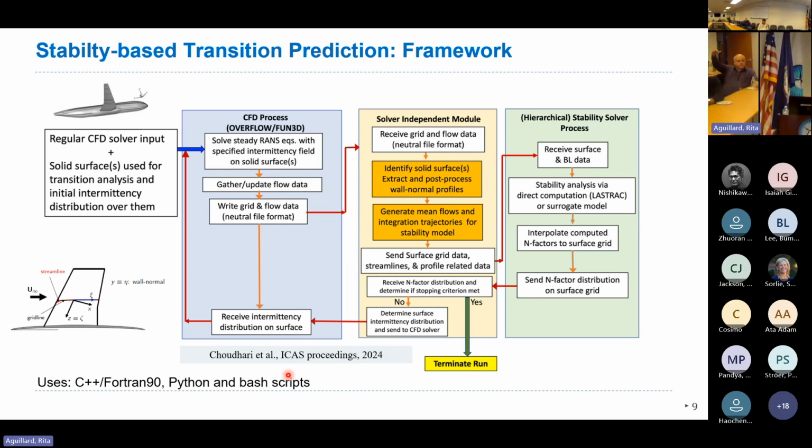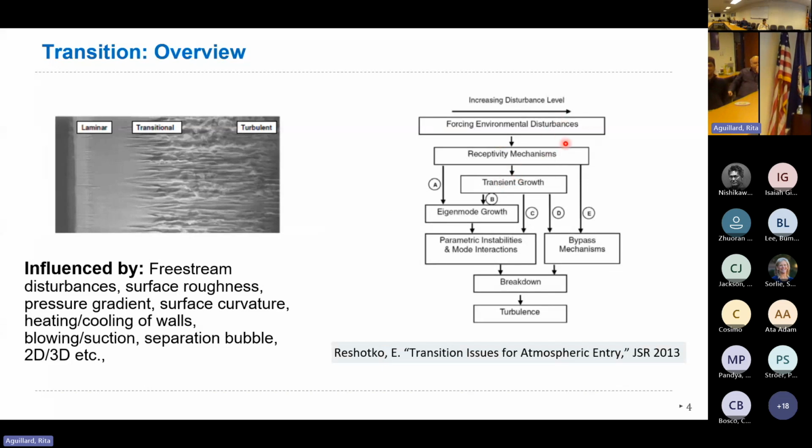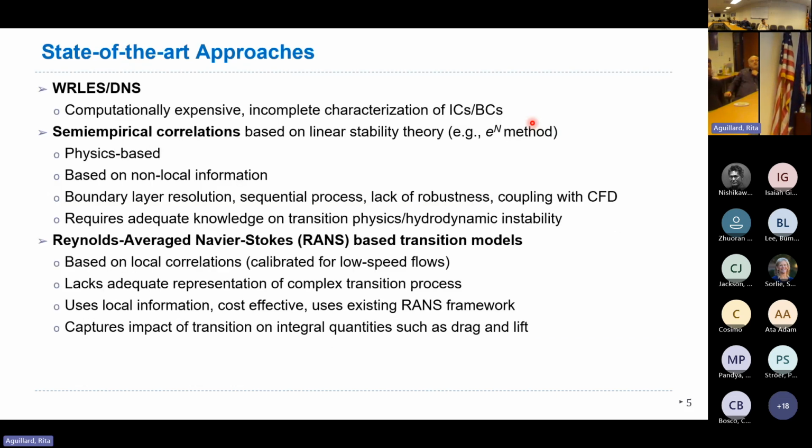But beyond the boundary layer, if the distance is very big, why worry there? It may not affect it, but it might matter. For example, if you have a turbulent wake coming through, you would have to actually address that to say that this region should be turbulent. That is a whole aspect I probably didn't talk about here. Receptivity is how much the far-field disturbance actually affects your flow. Things like that can have some impact, especially in turbomachinery.